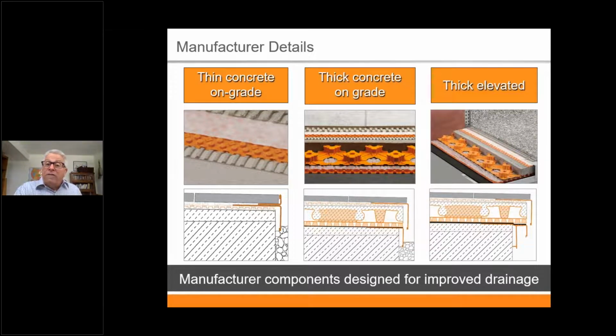You know, water does follow the course of least resistance, so this will greatly minimize the amount of efflorescence, the amount of that binding salt, that free calcium, that lime that's coming up through the surface. With the water being the vehicle to bring it to the surface, the water evaporates, leaving those calciums behind. It's unsightly. It's not really a failure, but it is a sign you have excess moisture content in the assembly and it's trying to get out. And the way it can get out readily is through the top. If you put a drainage mat in there, then you wouldn't have that. That's just below the tile.